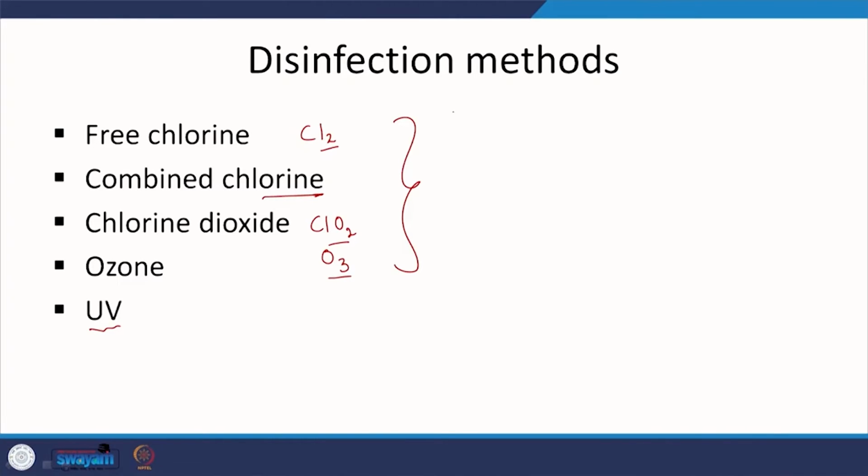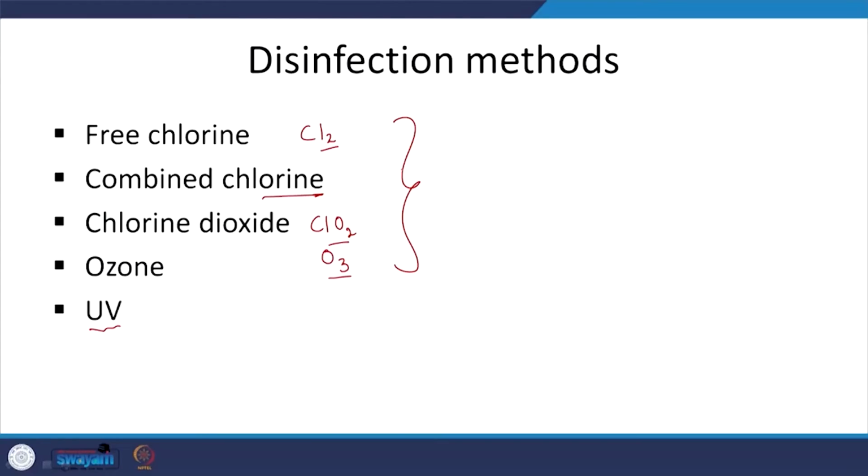Cell mass is also organic matter. So that is why you are going to add the strong oxidizing agents, which can degrade the cell layer components, or the cell wall, let us say. So there are different ways to bring about the inactivation of the microbes, and we will go about that. But as can be seen, one common aspect among all these top disinfection agents is that they are all oxidizing agents or oxidants. I think we will discuss this now.